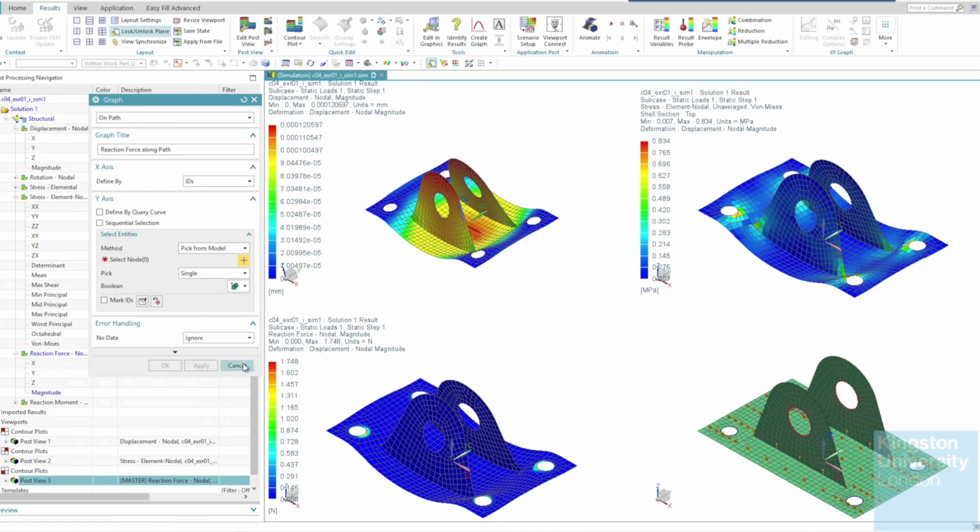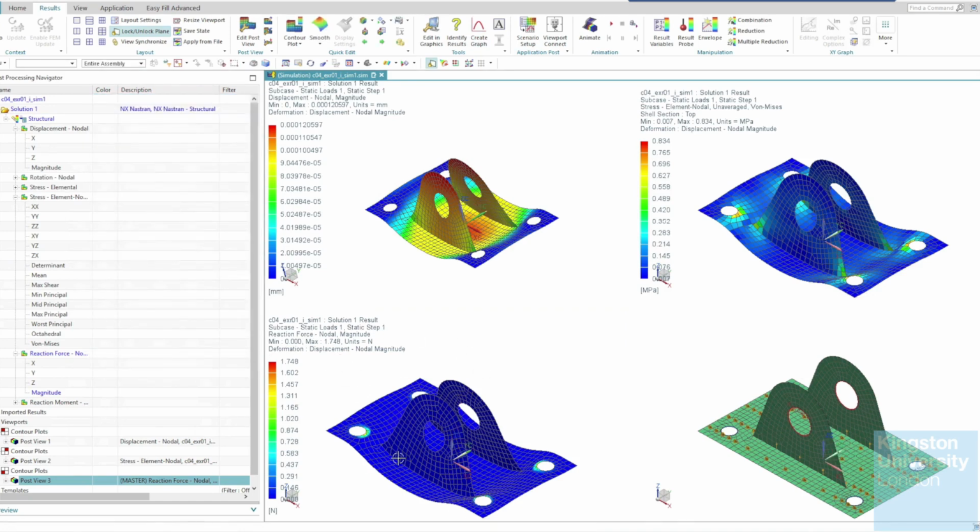Yeah, create the graph in a second, because basically it would be applied to there. So for the last one, I'm gonna create the graph for the stress. I'm gonna go with the von Mises again. This one, magnitude von Mises. I will go and plot it.